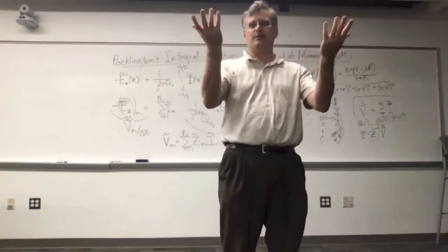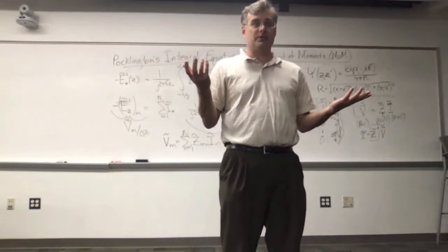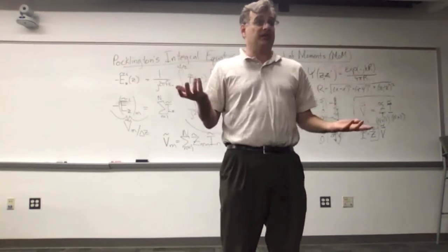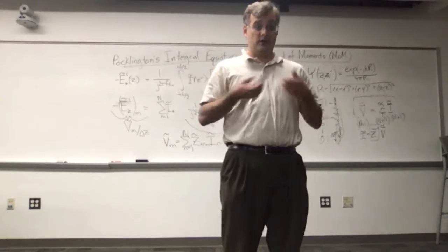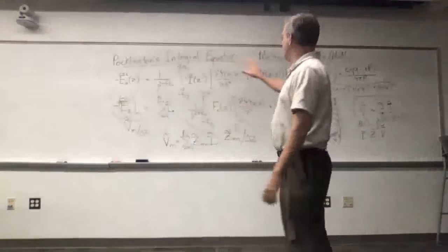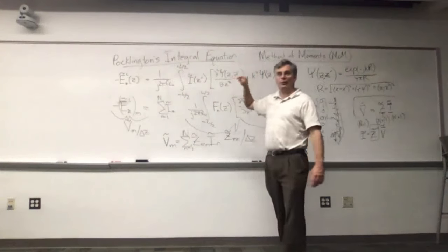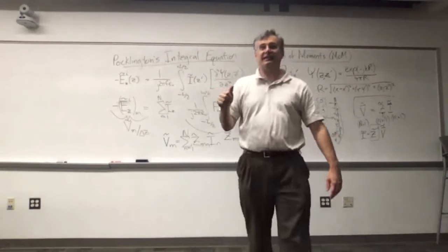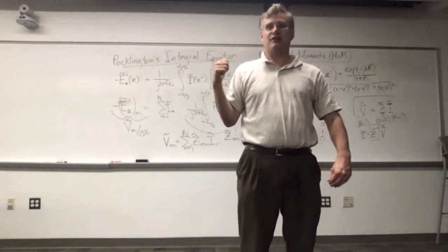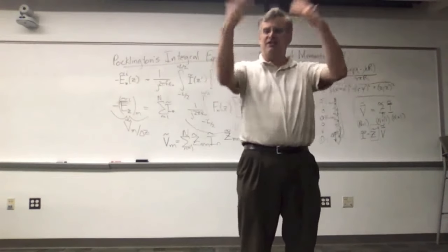We could apply those basic principles. Really, if you want to solve a transmission line equation, you're really solving Pocklington's integral equation for two bars of metal. The only thing is, this is a nasty thing to actually have to solve. So instead of solving it numerically every time, there are certain scenarios like the dipole and the transmission line where you just solve it in your head.